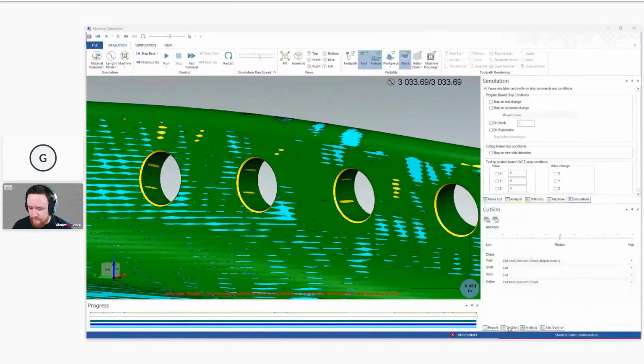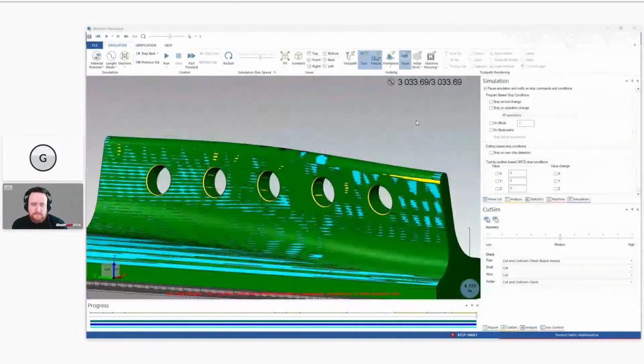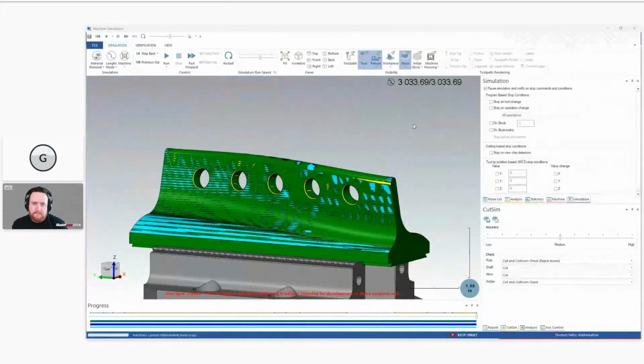accuracy settings. In the sim, we can change the accuracy here. Increasing that accuracy will slow down the simulation and take more horsepower to run, but it does give you a more accurate result. There's also, and I think you're going to touch on this coming up, the tessellation tolerance of the initial simulation when you run it, which is set to a larger value of about 7/1000ths of an inch. What that means is how tightly do we want the simulation to adhere to the toolpath motion?